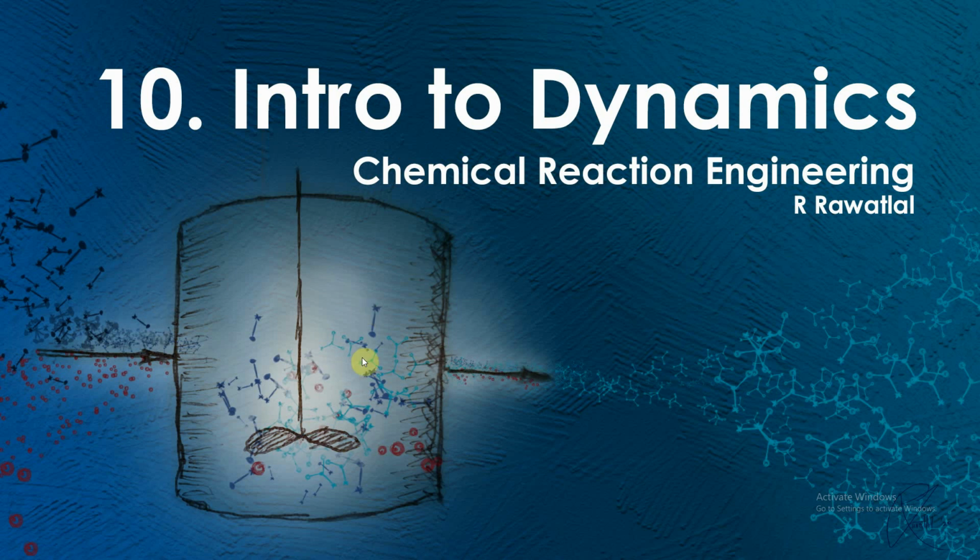So in a reactor, for instance, we have a complex interplay between temperature and conversion, and this may well make it difficult to identify which steady state will exist and occur in the reactor, because there may be more than one steady state available. It may also be the case that there's no steady state available. And so in contrast to the developments in the earlier coursework in the degree, we are now concerned about the presence of the steady state.